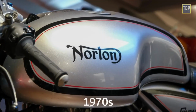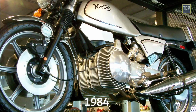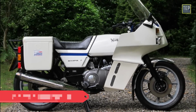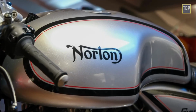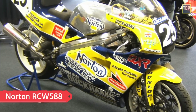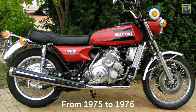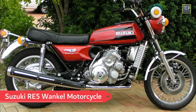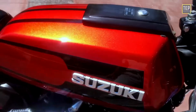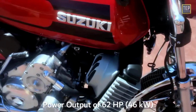Norton spent most of the 1970s fiddling with prototype rotary-powered bikes, but it took until 1984 before finally creating its first production Wankel engine motorcycle, the Norton Interpol II, as a police version. Subsequent Norton Wankel bikes included the Norton F1, F1 Sports, RC 588, Norton RCW 588, and NRS 588. From 1975 to 1976, Suzuki produced its RE5 single-rotor Wankel motorcycle. It was a complex design with both liquid cooling and oil cooling and multiple lubrication and carburetor systems, having a modest power output of 62 horsepower.